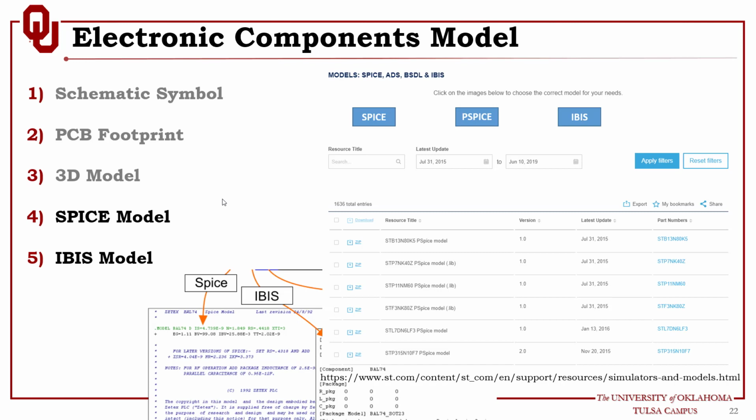Now, if you cannot find the SPICE model or signal integrity model and you don't care about signal integrity analysis or SPICE analysis within Altium, you don't have to worry about it. It's not necessary to integrate these models when you create a component in Altium Designer, because sometimes you might want to do your SPICE simulation in third-party tools like LTspice, for instance, which is what I usually do. I don't count on Altium Designer to do SPICE analysis. Sometimes I use signal integrity analysis, and we can talk about that in our coming sessions.